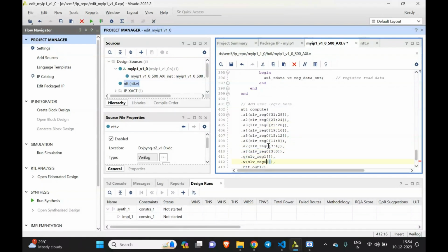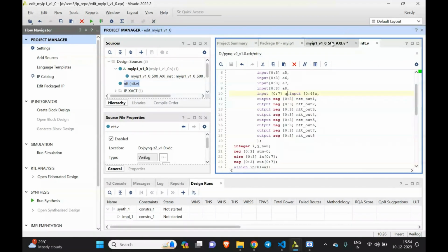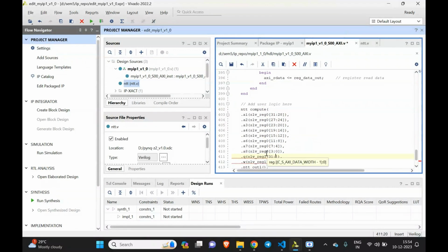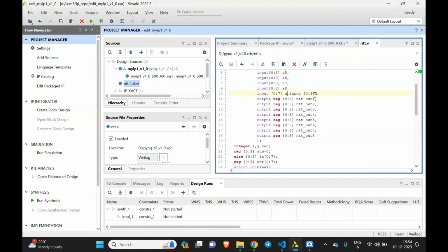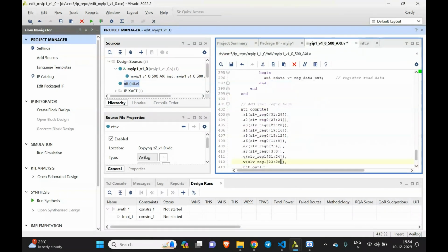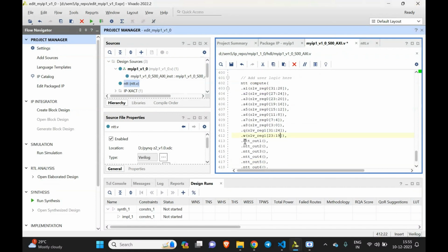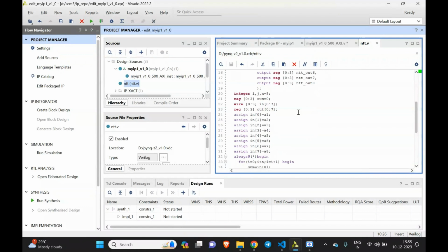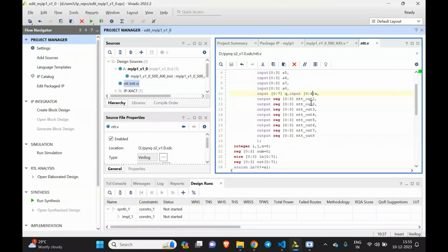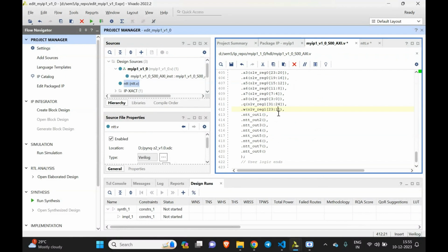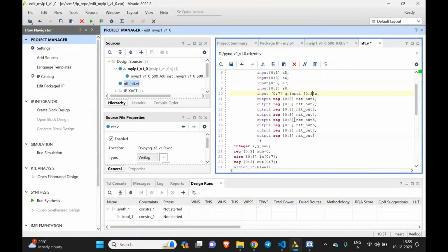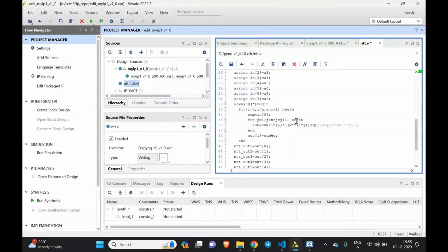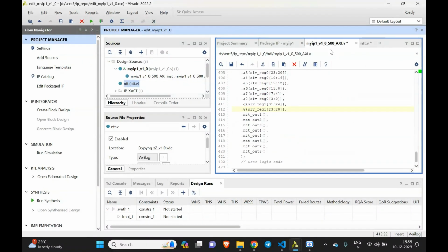Here we are going to use the next registers, and we can see here that the prime modulus is 8 bits wide. So we'll use 8 bits here, and the twiddle factor is 5 bits wide. We can change it to 4 bits here so that everything is even. It doesn't matter anyway because the twiddle factor won't be that big. So this is not going to affect the code now.